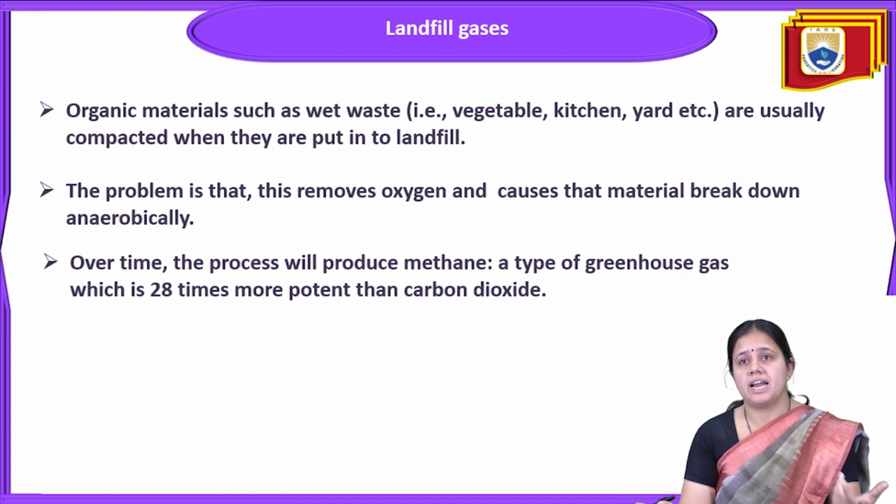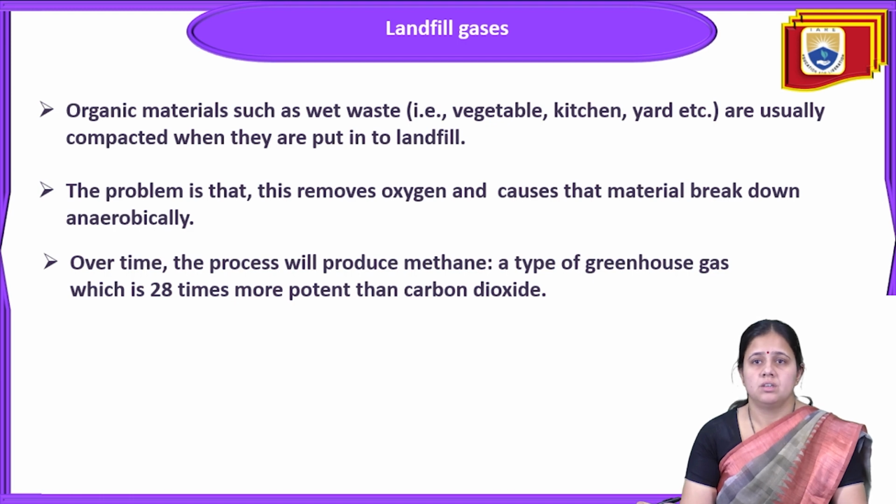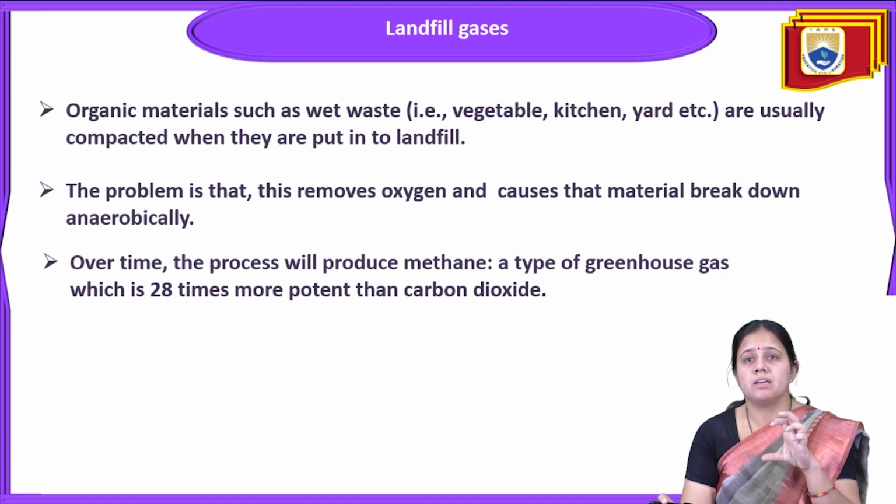So what is landfill gas? Why will there be leachate collection and landfill gas? In the landfill, what happens? Some organic materials are there, like wet waste, vegetable, kitchen or yard waste. When they are put in the landfill, as I have discussed, we compact the waste, and only by compaction do we keep the waste.